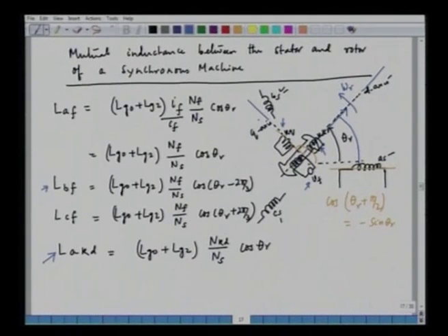We have to transform all variables of the stator, physical stator, that is phase A, phase B and phase C of the stator, to D and Q axis. Of course, these axes are hypothetical. I mean, the windings corresponding to D and Q axis are hypothetical, but we have to transform the physical ABC variables, voltages and currents, to the D and Q axis housed on the rotor. Because our reference frame is a rotor reference frame, we will have the following expression.